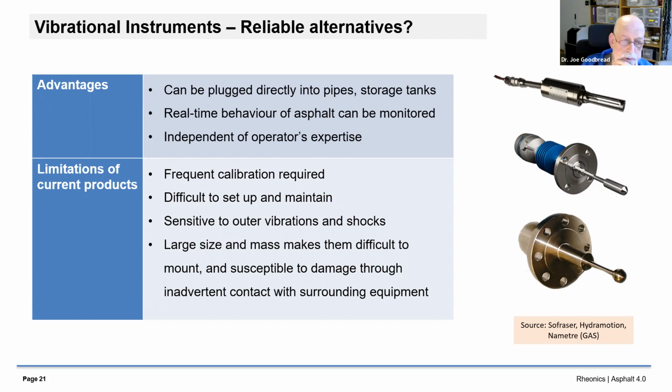It twists to a very, very tiny angle. And the viscosity of the fluid that it's immersed in damps out those vibrations. So by measuring the damping of that resonant element, using special electronic circuits, it can estimate the viscosity of the fluid that is doing the damping.